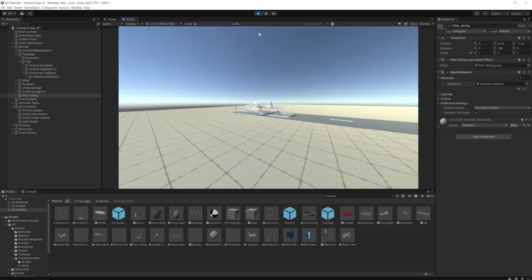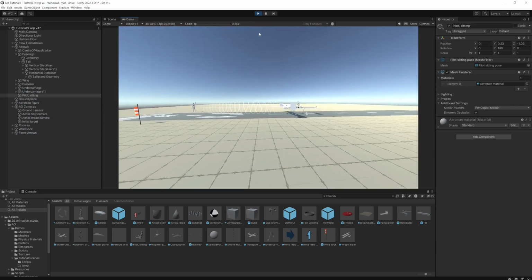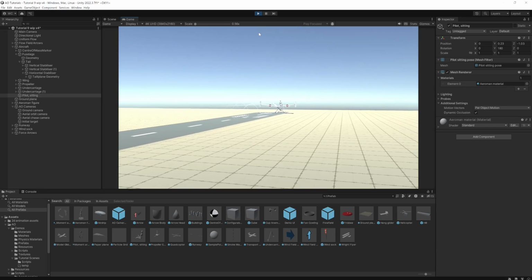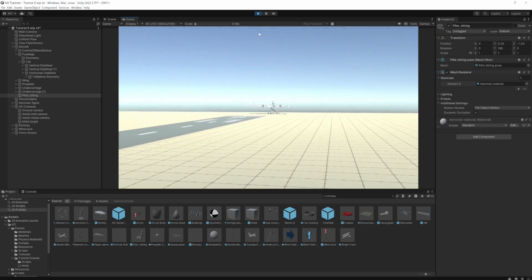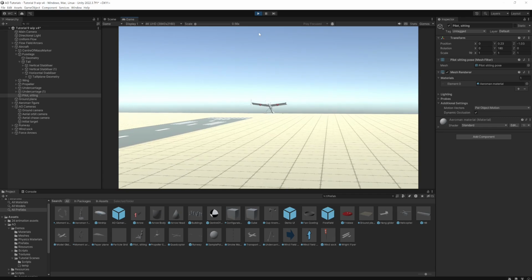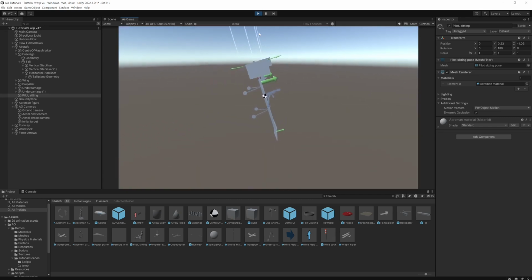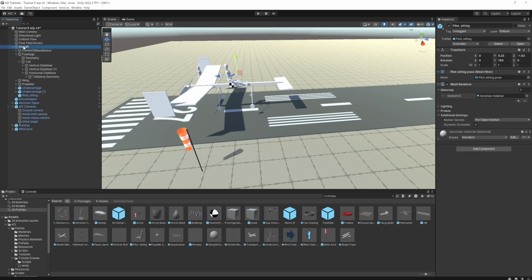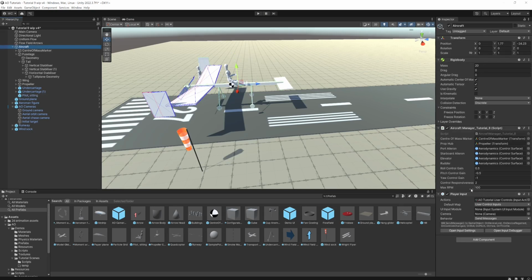Okay, going down the wrong way, but actually, even on full thrust, we've not really got enough speed for takeoff. So what's happened there is that we've made the propeller 80% smaller, but we haven't increased the maximum speed it can go at, so we're not getting enough thrust. So let's go and change that. So the maximum RPM was limited to 100. We've made the propeller 80% of its size, so let's actually increase that to 150, so it's spinning around faster.